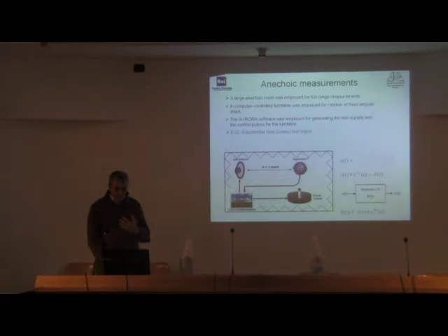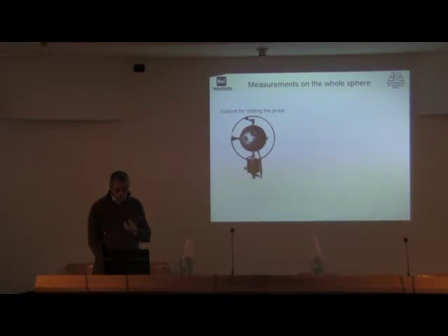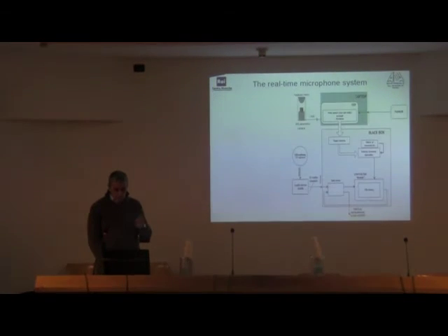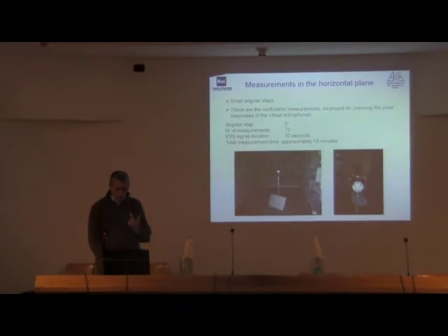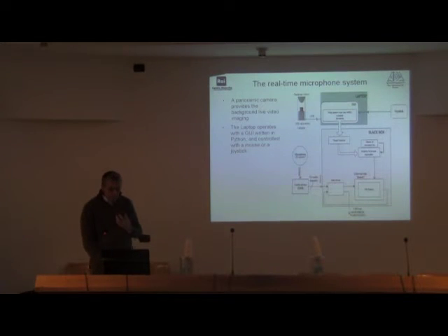Measurements were done inside the anechoic room for capturing the spatial information of our microphone with the sine-sweep method, of course. This is the support for rotating the microphone inside the room. And then we also made a reference measurement with a turntable just for controlling how the pattern comes out. After we designed our inverse matrix of filters, we designed a real-time microphone system.